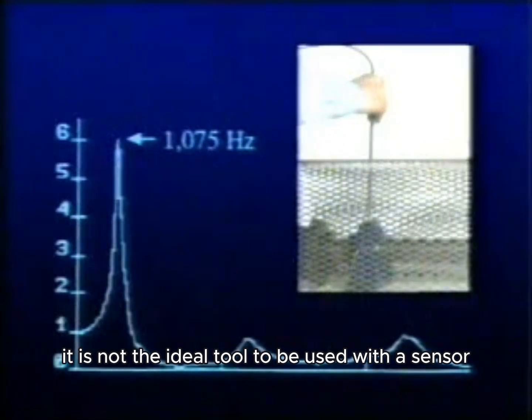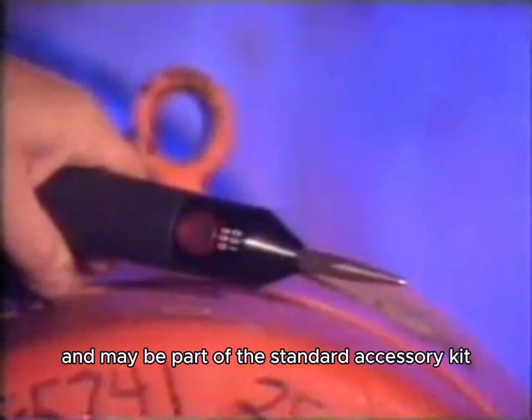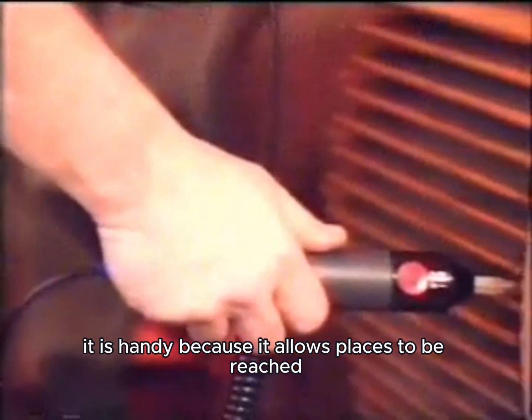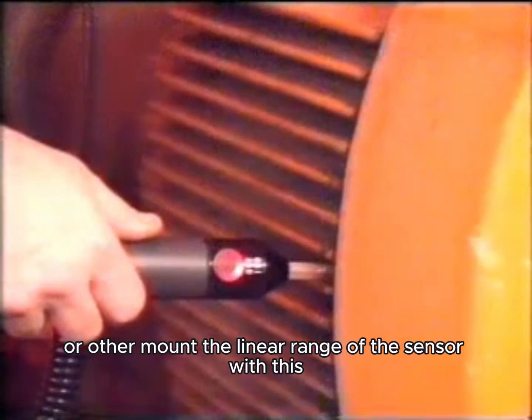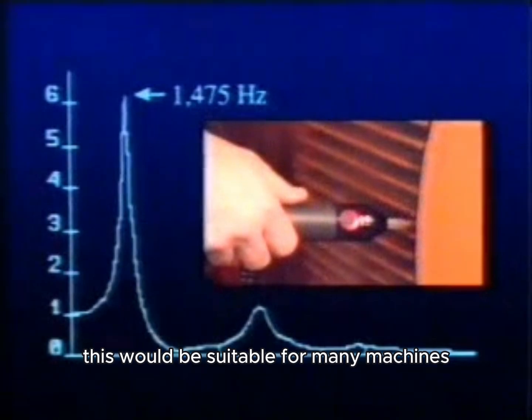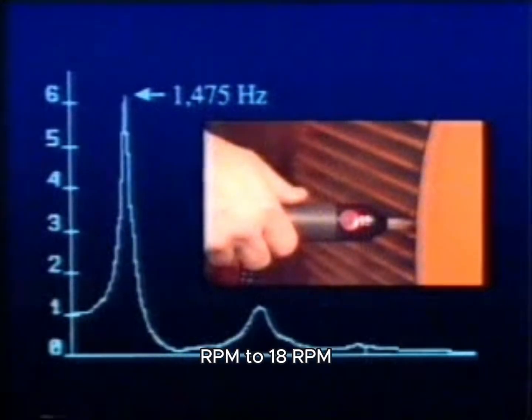This 2-inch stinger is also a very handy tool and may be part of the standard accessory kit with your analyzer. It is handy because it allows places to be reached that could not be accessed with a magnet or other mount. The linear range of the sensor with this 2-inch probe is approximately 500 Hertz. This would be suitable for many machines that have shaft turning speeds ranging from 1,000 RPM to 1,800 RPM.